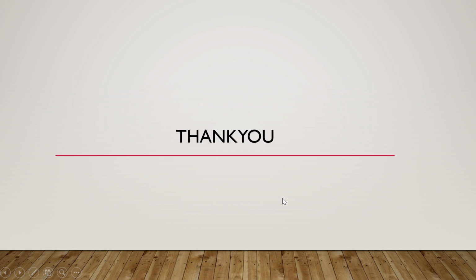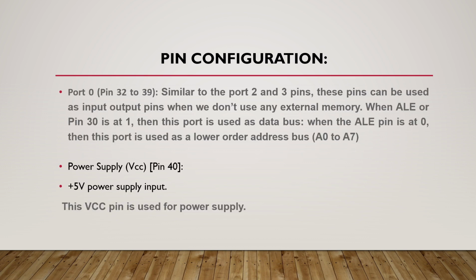It will transmit the data from the microcontroller. When the ALE pin is at 0, this port is used as the lower order address bus. It will take the address from the microcontroller.